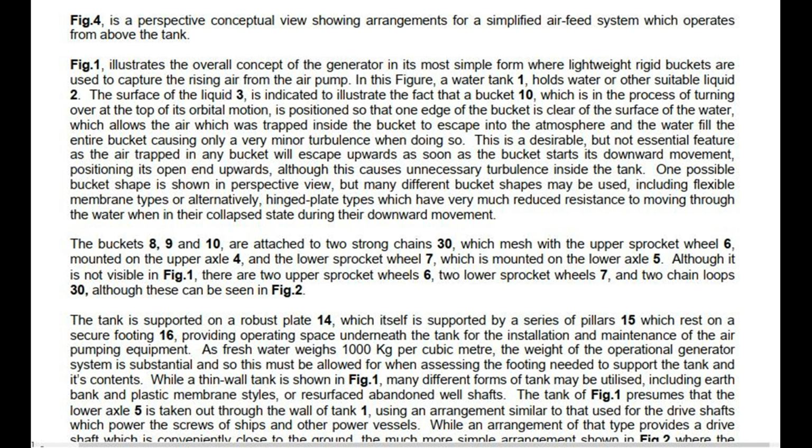The tank is supported on a robust plate 14, which itself is supported by a series of pillars 15, which rest on a secure footing 16, providing operating space underneath the tank for the installation and maintenance of the air pumping equipment. As fresh water weighs 1,000 kg per cubic meter, the weight of the operational generator system is substantial, and so this must be allowed for when assessing the footing needed to support the tank and its contents.